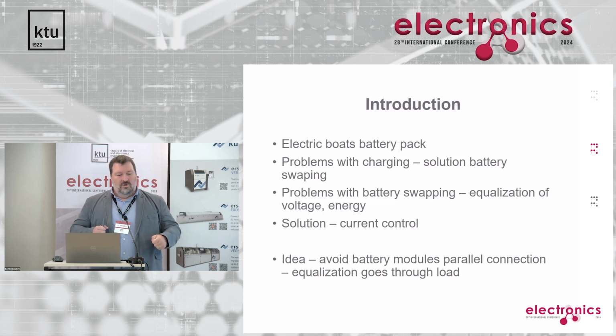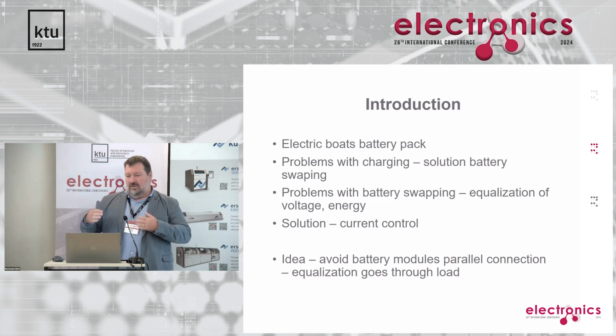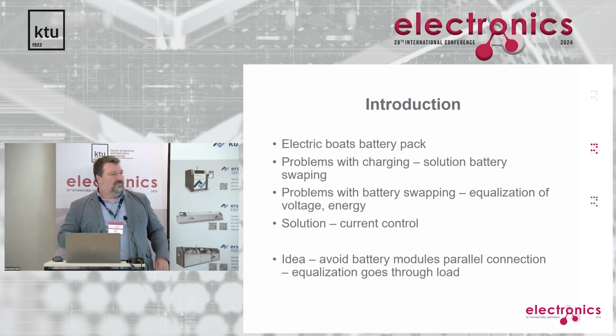So when you put a new fresh module in the battery pack, there should be no equalization current, but that balancing equalization should occur through load and regenerative braking over some small set of very simple rules.